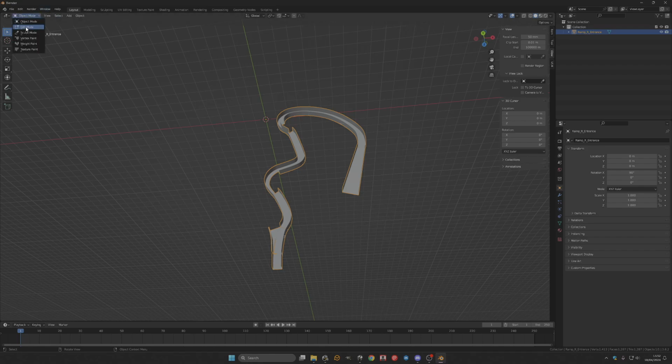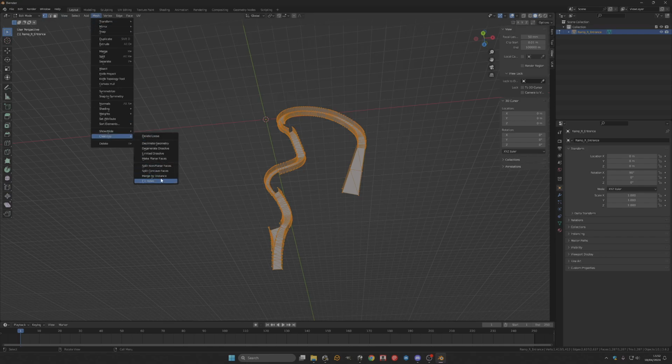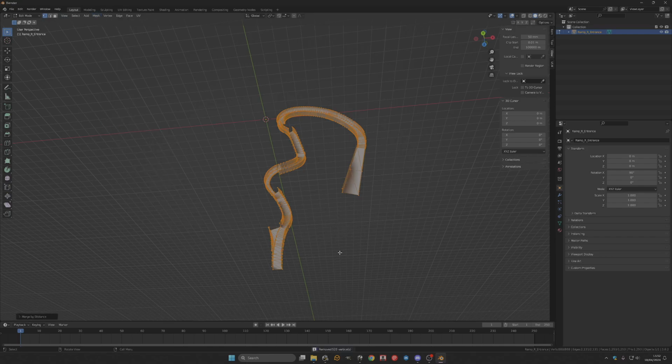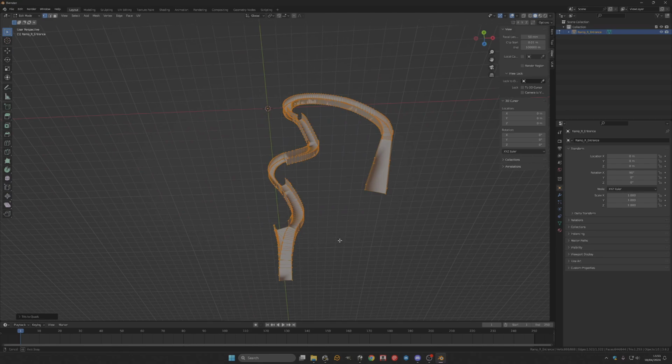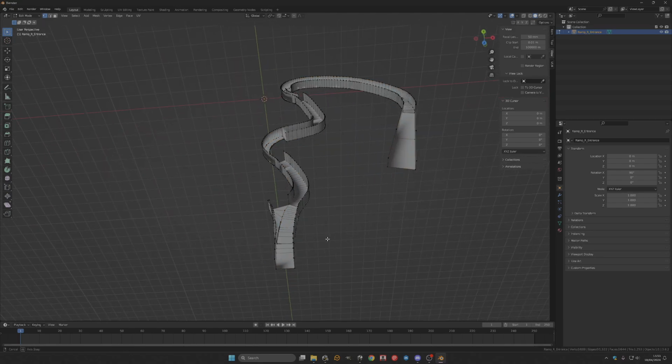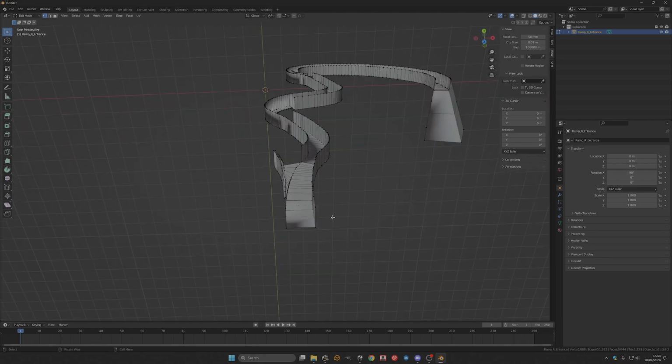Go up to here and click edit. Press A to select all. This is what I always do. VPX exports things with too many vertexes, which are these dots. So go to mesh, clean up, merge by distance. It gets rid of 525 dots. Next thing you do, go to face, triangles to quads. And that gets rid of another load of nonsense. So that's how you sort of prepare it really roughly.